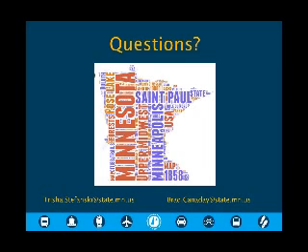Okay. What format is your as-built data in? Well, we asked for UTM, I think, for our projects for the asset information, and then it is in just an ASCII. We also accept shapefiles or a geodatabase. And then we get the LAS files for the scanning information.